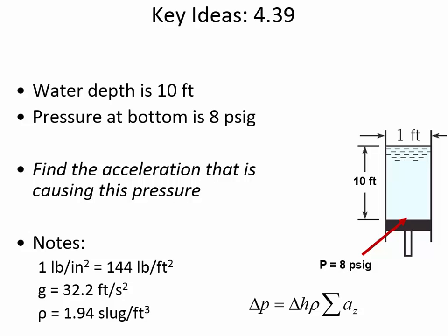All right. So this is what we've adapted our hydrostatic equation to so far. What's the limitation of this expression? Only when the acceleration is vertical, and it is here. This cylinder is confining the movement of the liquid to up and down because of the cylinder walls. And so there's no side-to-side acceleration. The full-blown Euler's equation, which we'll get to next Tuesday, takes us way beyond, but you can solve it this way.